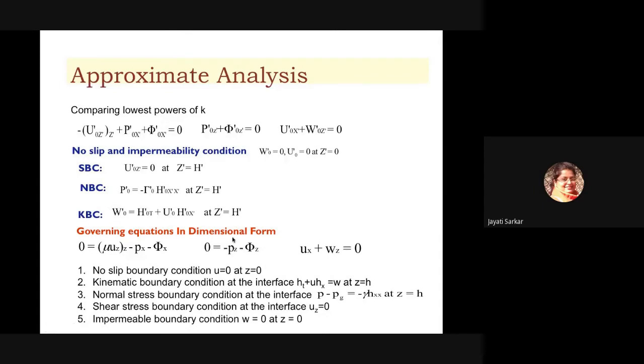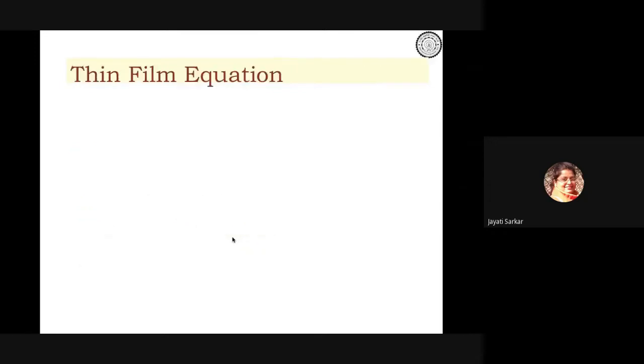The main thing in solving a thin liquid film equation, which is definitely different from maybe a fluid in a pipe flow and other things, is that first, the body force is important, which is different. Also, we are considering an approximation that we don't make for normal fluid flows, because here the viscous terms are quite higher compared to the inertial terms. So once we do this, we can get the profile.